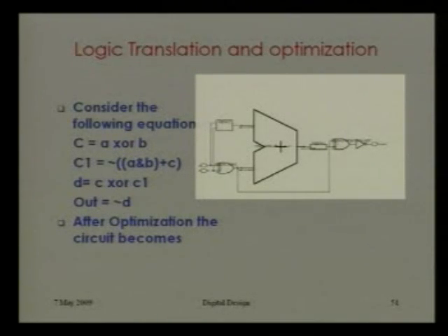This is one. I am just mentioning what are the very important things. Say you have given some circuit, and after simulation or logic synthesis you are getting a different thing, because every time the tools are written so that they optimize that thing. So be careful about that.